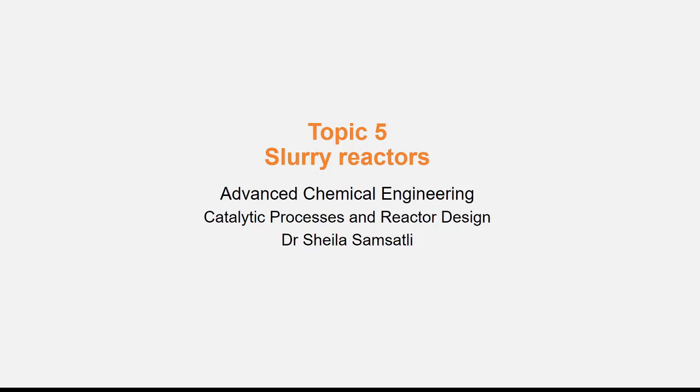Another reason for using slurry reactors is that you have a gas phase reaction catalyzed by a solid that is highly exothermic, and you need to carry it out in the liquid phase for heat management. Many complex reactions in chemical industry are performed using slurry reactors. It is important that you understand how they work so that you can model, analyze, design, and troubleshoot them.